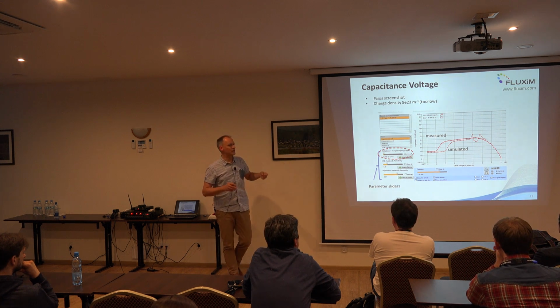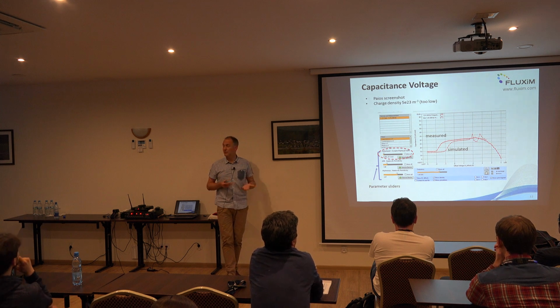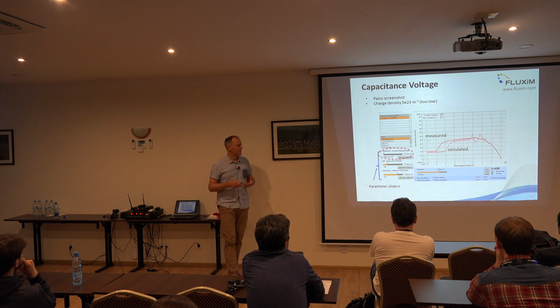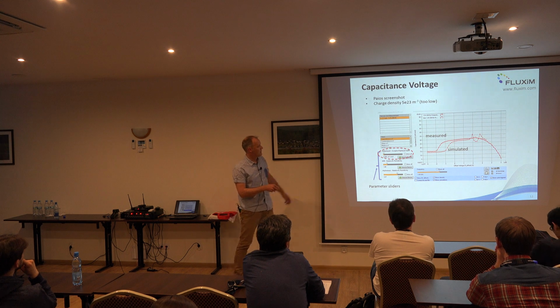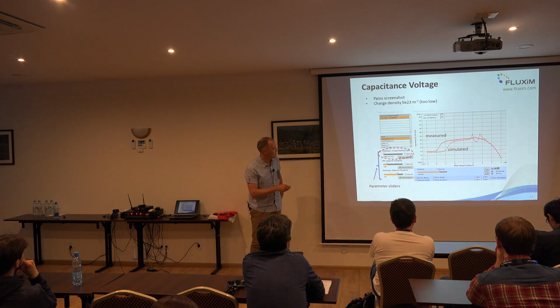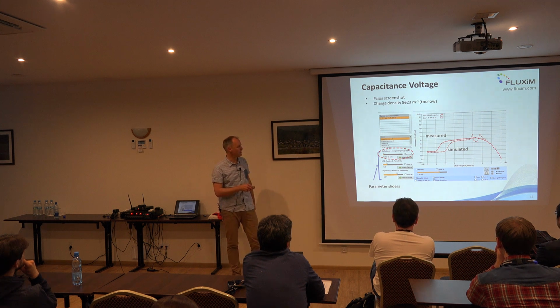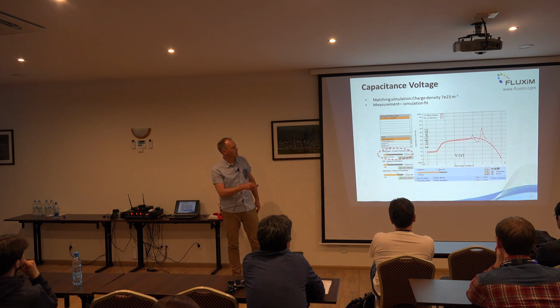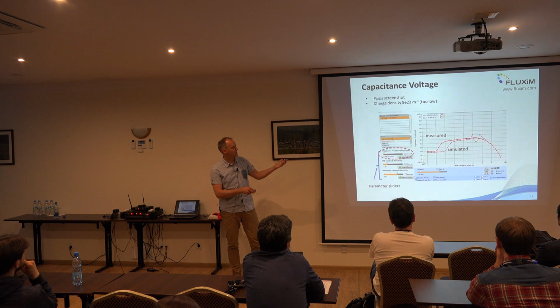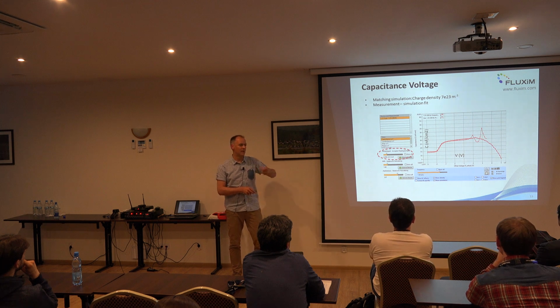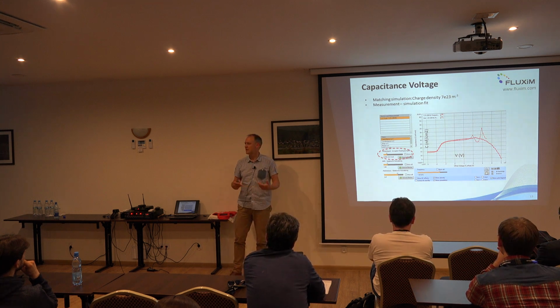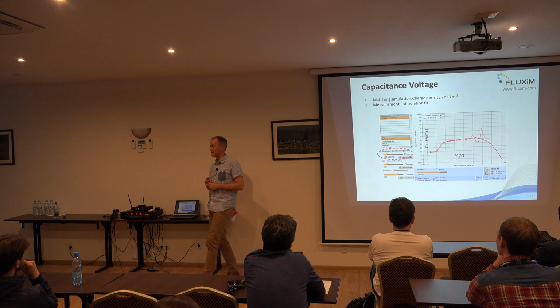So instead of doing a fit, there's also an option to do a parameter sweep. And you see here a slider. So if we now change the value of the polarization sheet charge, I will get to that later on. But if we change the value of this quantity, you see that the simulated curve moves to the left. So basically you can also manually adjust the parameters by sweeping the values until it fits. That's the alternative to using an automatic least square fit.